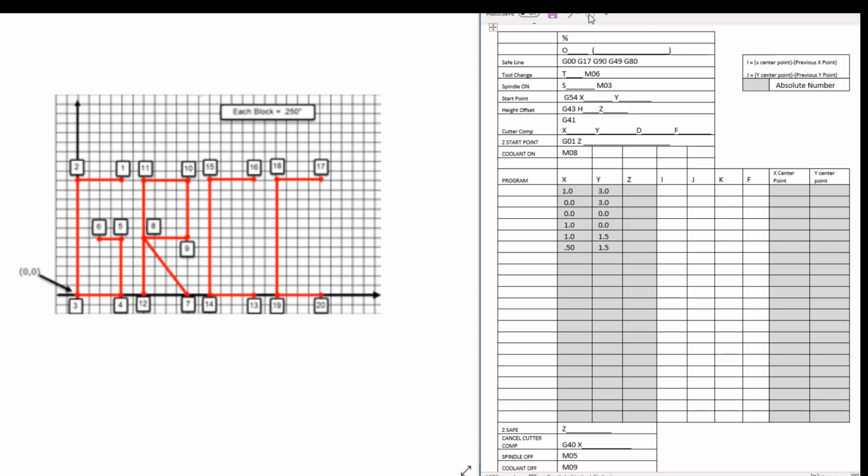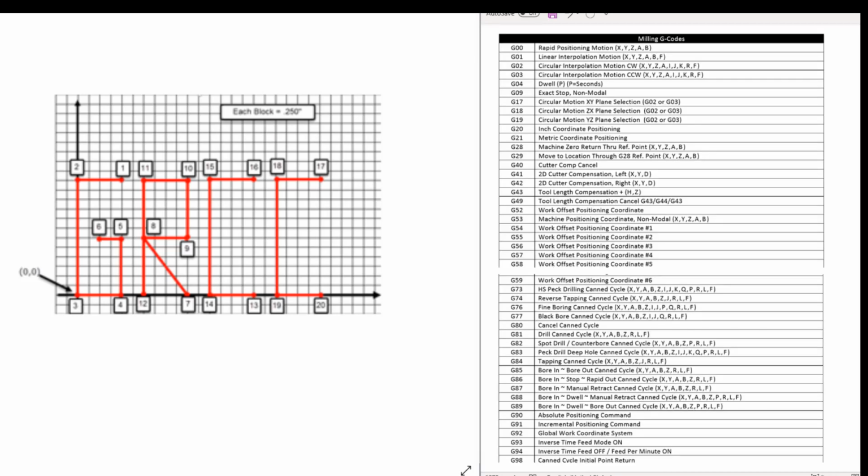Now we're going to jump over into the G code, G and M codes, and the third category, letter codes, like I like to call them, to talk about some of the functions of the machine and how we can finish filling out this program. Okay, so what we're going to start with here are G codes. G codes are movement commands. You're telling the machine to move.